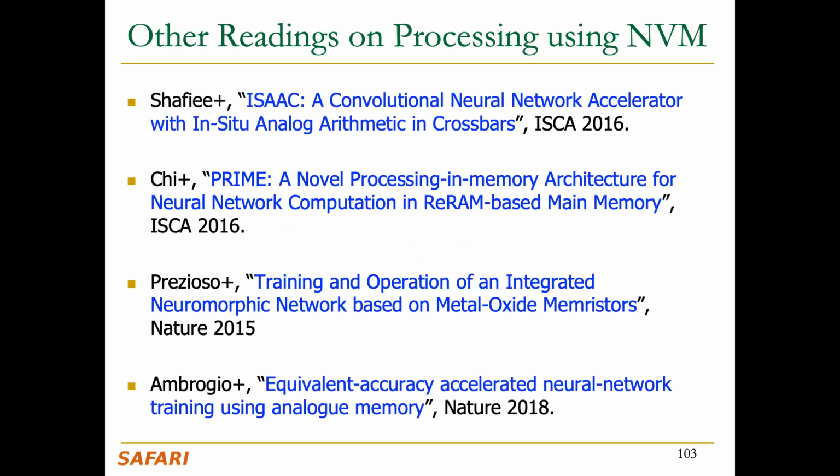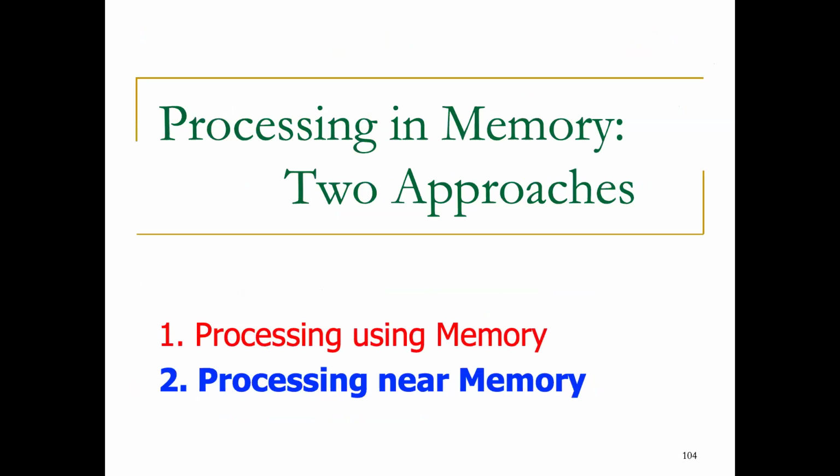And as I said, emerging non-volatile memory technologies are capable of doing even more. So DRAM is, I believe, limited to bit-serial operations, although people can innovate better, perhaps. But emerging memory technologies have a matrix-vector or three-dimensional structure such that you can actually feed analog inputs to weights that are stored in a two-dimensional array. And you can actually do vector multiplication on the matrix that's stored in the array, which is actually this thing that can accelerate machine learning, as you can see.